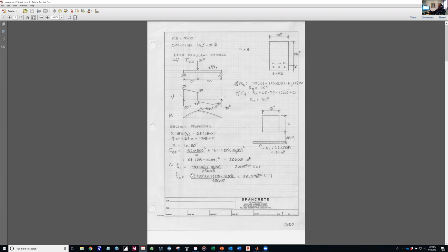And factored loads are never in the elastic range of materials. So all of this that you see here, I cracking, M cracked, finding the short-term deflection, finding long-term deflection, telling me what the stresses are with f sub c and f sub s, these are all based on service loads.